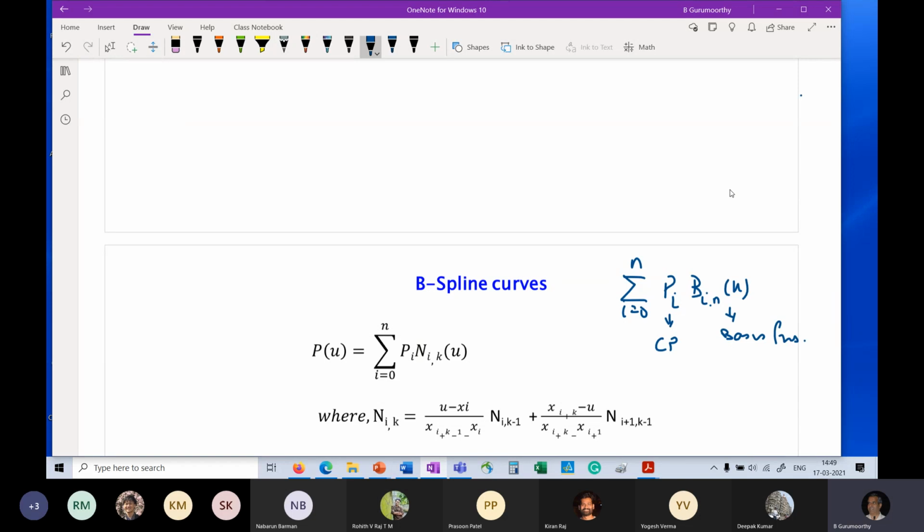Just like your xi plus yj plus zk, where x, y, and z are the values, and i, j, k are the basis vectors. Here, these are the basis functions, and the P_i's are the points. Here also the same thing. P_i in this instance are the geometric input from the user, in this case points, and N_i,k(u) are the basis functions.